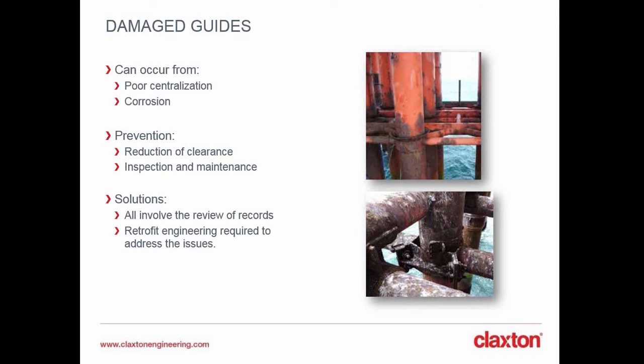For the cellar deck, platform personnel should be able to check quite often the state of the equipment and whether they witness excessive movement. Issues at this level can be quite indicative of problems in the splash zone level. So if any problems are detected, it would be a good idea to then check the centralizers at the guides and splash zone levels just to see if they're presenting any problems.